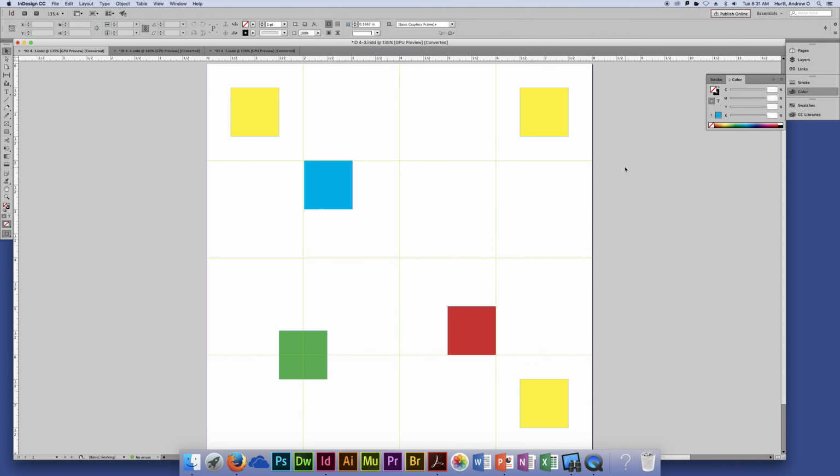And that's essentially aligning objects. What I tend to do a lot, when I copy and paste or am creating new objects, is hold Shift and Option-drag. Holding Shift will just keep it in alignment with the object that you're copying, so you don't accidentally drag it down a little bit, and it saves you a step.